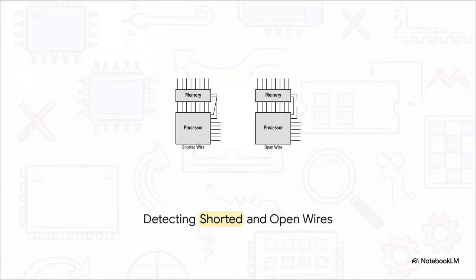You see, writing memory test code isn't just some abstract software exercise. It is literally the act of checking the physical reality of your board. We're hunting for highly specific physical defects here. We're talking about shorted wires where two data lines are accidentally touching, or open, broken wires. Our code also has to catch improperly seated chips, where a tiny bent pin completely misses its socket. Yeah, the classic cause of a ruined weekend right there. This is the physical, real-world reality our code has to uncover.